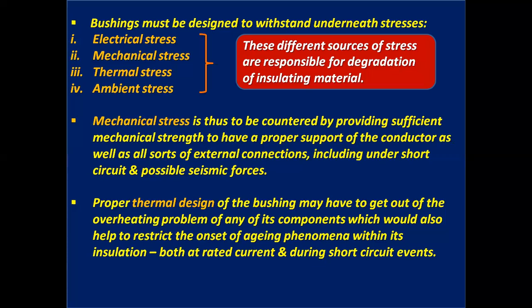Proper thermal design of the bushing avoids overheating of any of its components, which also helps to restrict the onset of aging phenomena within its insulation, both at rated current and during short circuit events.